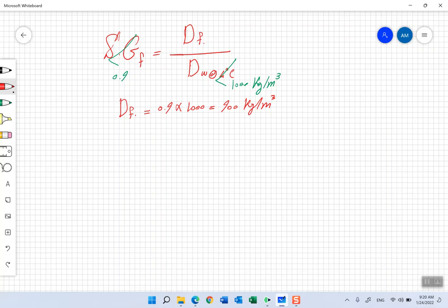As I showed you 1 minute earlier, each hydrometer is divided into a certain interval. This one can measure the specific gravity between 0.7 and 0.8. So what if I have a fluid that has a specific gravity more than 0.8? This one won't be able to measure. So you will go through the rest of the hydrometers to check which one will work.